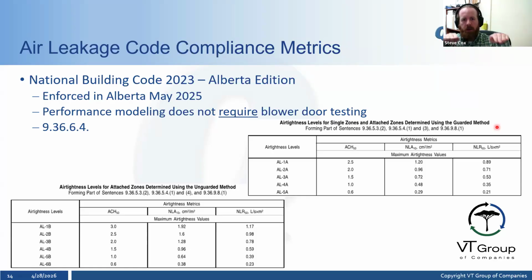So I'm going to go 15, 20, 25, 30, 35, 40, 45, 50, all the way up. And what happens is I'm taking out that party wall, that demising wall between the units, as a point where air can leak, because the fans are going up at the same pressure. So they're depressurizing at the same rate. So now the only leakage I'm getting through that middle fan is air that's coming from outside. Okay, so that's a guarded test.